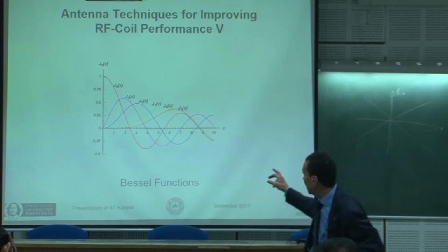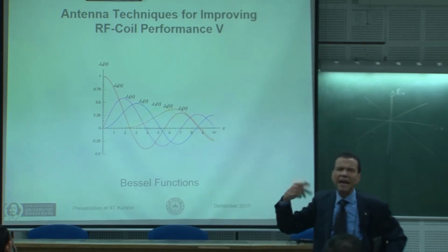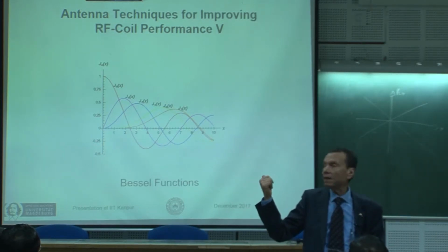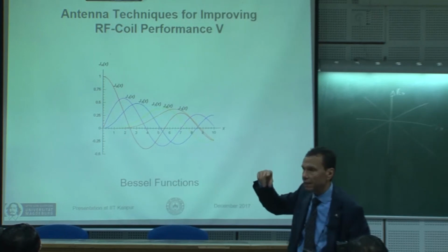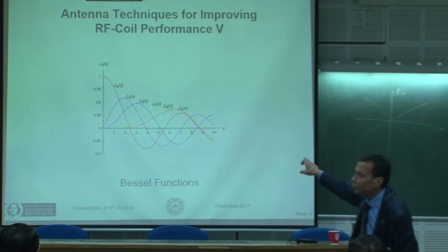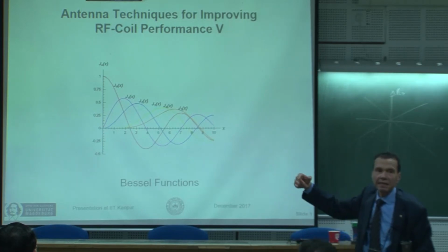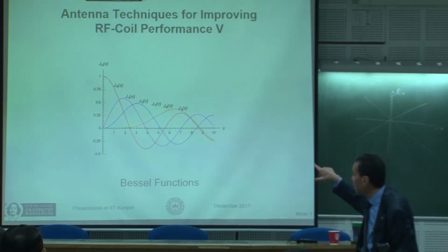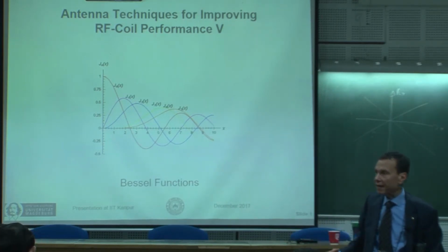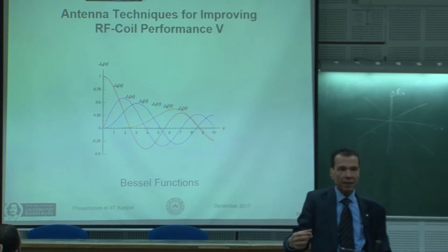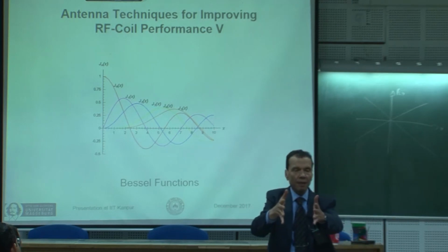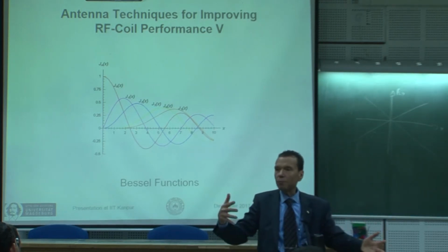Now the array elements are actually, no, not the array elements, but the beams themselves are the different distributions here. And the signals themselves are what will be fed to J0, what will be fed to J1, and so on. So actually, I can have a beam-forming network, which is called a Butler matrix. The Butler matrix is a system. The outputs are the antennas. The inputs are the signals.